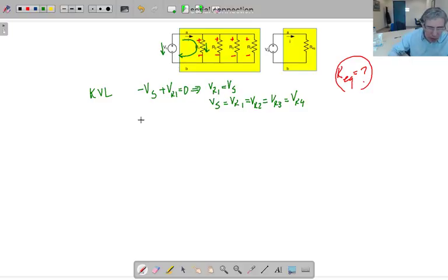Another thing that we could write here in order to calculate the equivalent resistance value is the current. So this element's currents are I1, I2, I3. I cannot choose these current references randomly anymore, because I've got to choose them according to passive sign convention, otherwise I'm going to face problems that I can't solve.